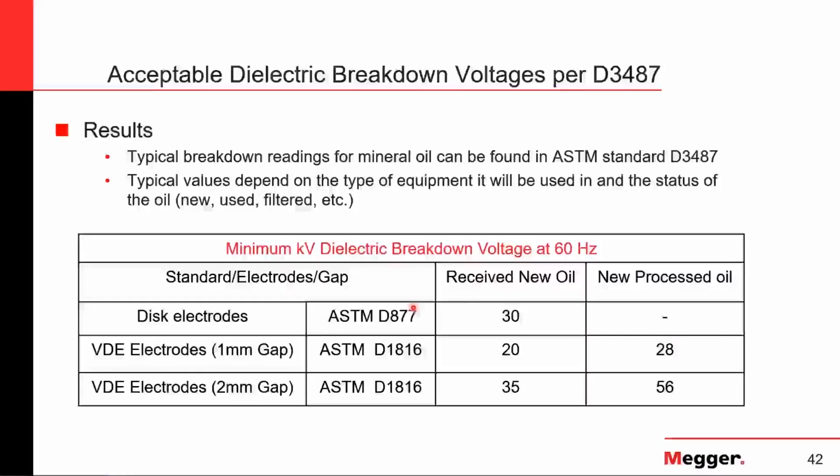We look at the IEEE recommendations in terms of those minimum values recommended for dielectric breakdown voltage testing. We will have different categories depending on if the oil is new, as received in new equipment, or if it's in service or service age oil. And also different values depending on the nominal rated voltage of the equipment we took that sample from.